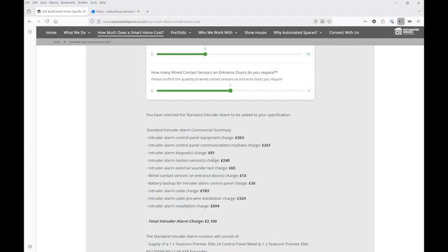Whereas if we have a contact sensor on the door, what we can do is you can put your PIN code in, and then the countdown won't stop until the door is opened and then closed again, signifying that you've actually left the property, and then the countdown sequence starts. Just gives you a bit more of an orderly exit to your house when you're trying to leave.